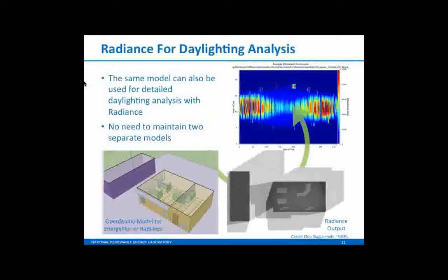So EnergyPlus, its notion of compartments within a building are really basically just thermal zones. It's all driven by what the thermal zones are. And unfortunately, that translates directly into the geometry that gets exported and calculated for daylight distribution in space. So your thermal zone boundary is your space boundary.